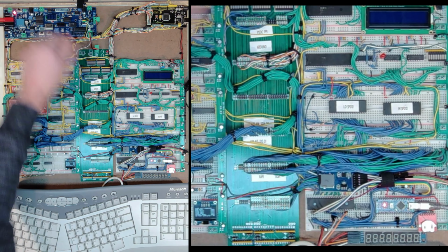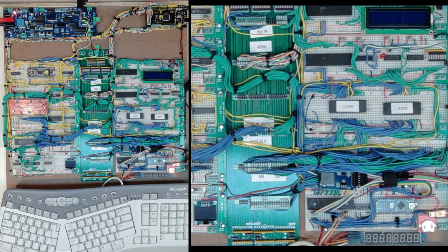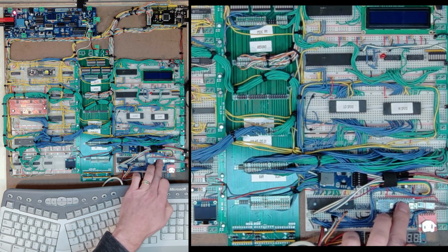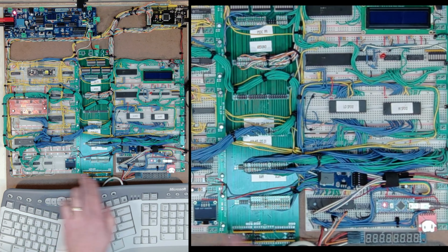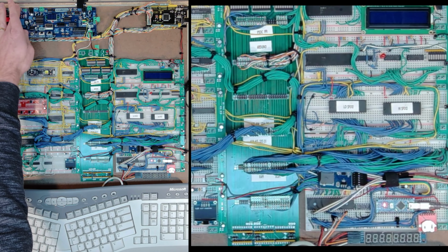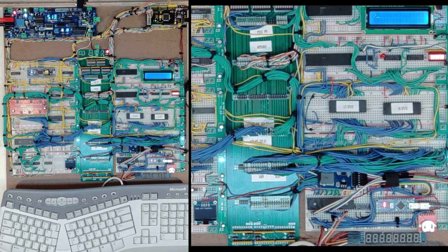But if I lose power to my Nano, which I'm going to just pull, and I plug my Nano back in, I can see it initialize the LCD right away, and now when I turn it on, I'm probably going to be back at 0. That's what you can see. So 7 seconds since I applied power, basically. And if I hit F1, I can see it's now counting up. If I go F2, I'm setting it back to 8 o'clock, and now it's going to count up from 8 o'clock. Everything seems to be working other than probably the most important part, which is the retention of that information.